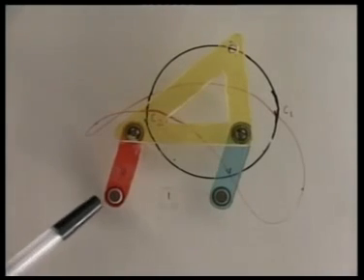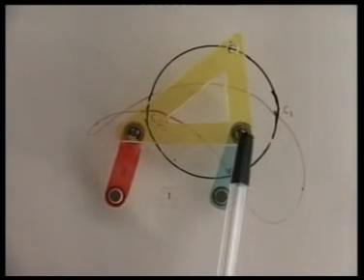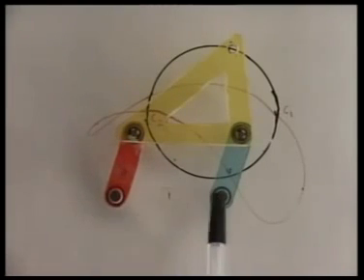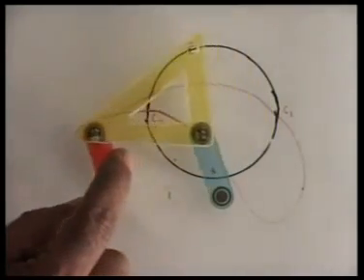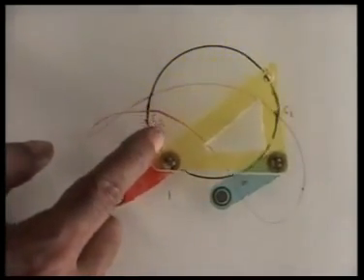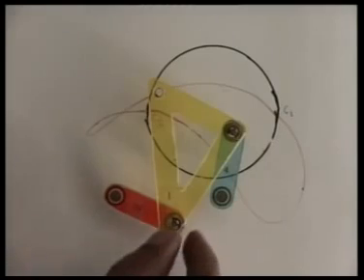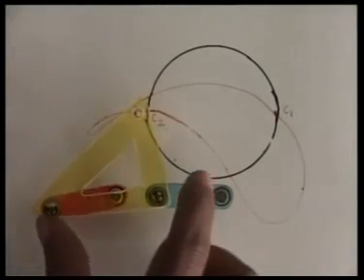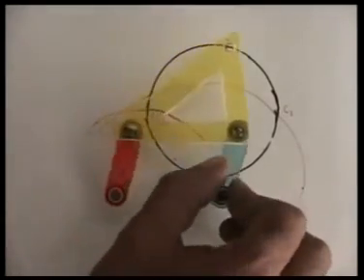Let us now look at the model of this parallelogram linkage. Here, this red link and this blue link are of equal length, and this coupler, which is the yellow link, has the same length as the fixed link or the distance between these two fixed pivots. As we see, this parallelogram linkage, when it moves, always remains a parallelogram. However, when all the four links become collinear, there is a possibility that it flips into anti-parallelogram configuration and it does not move as a parallelogram linkage. Again, here, if sufficient care is taken, one may transfer it back to a parallelogram linkage.